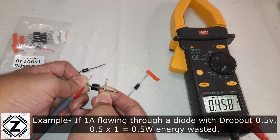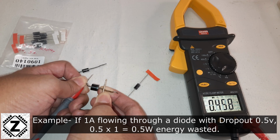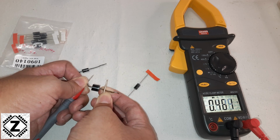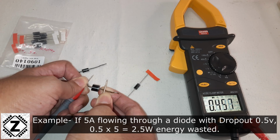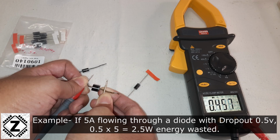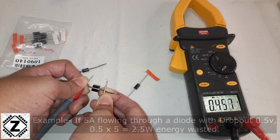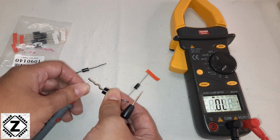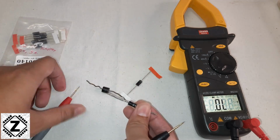So what is this reading? This reading is known as the drop-out voltage. Now 0.458 is the amount of voltage that this diode will drop. Or in a better sense, you can say that this is the amount of voltage that this diode will waste. Basically, it's going to convert it to heat when the diode is working. Alright, so that is 0.457 for a general purpose silicon rectifier diode.